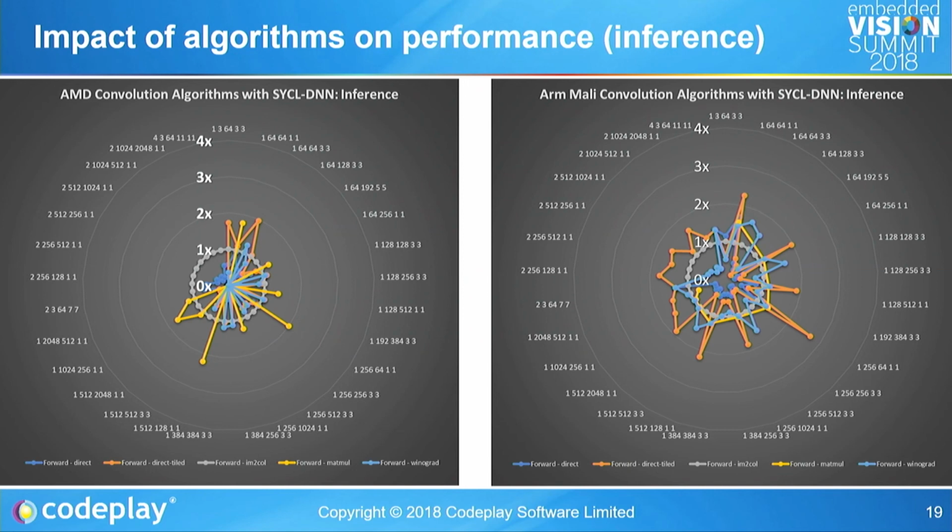One of the things that we do have to do is manual DMA, which is something that we as a company had to do with the PlayStation 3 hardware and actually PlayStation 2 hardware, so we have quite a lot of experience of it. With GPUs, you don't have to manually DMA stuff in, whereas with DSPs you do. GPUs just hide the latency by running huge numbers of threads. On a DSP-type device, you have to control that memory much more manually.